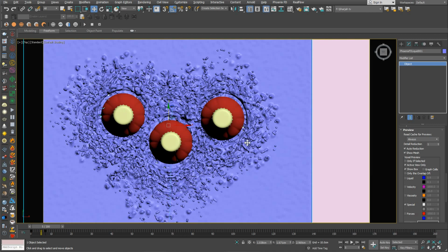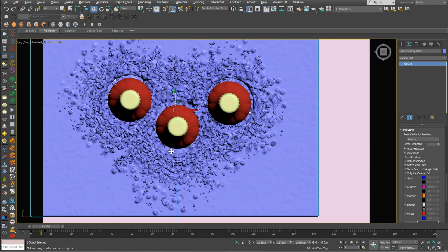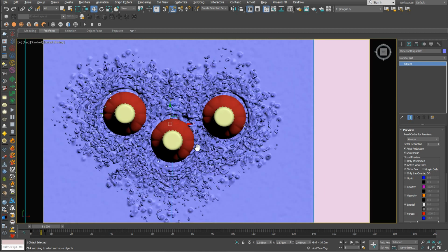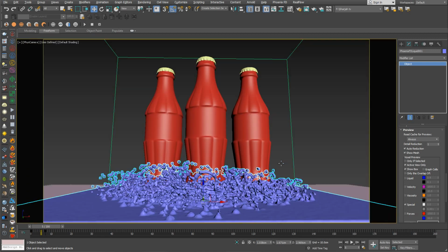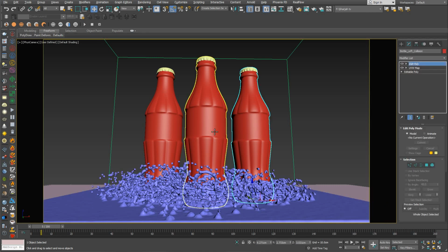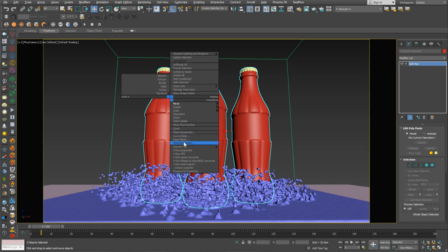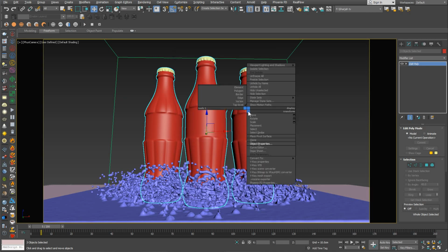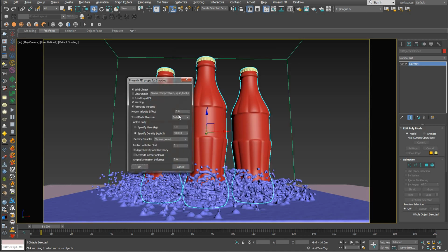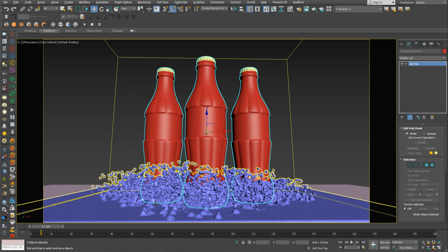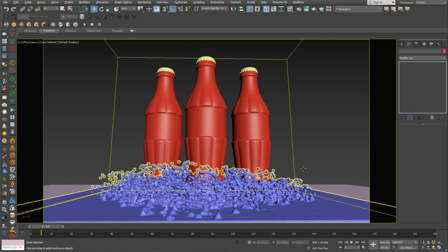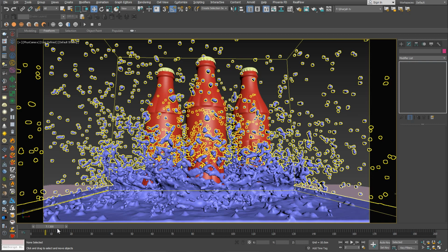Still, I can reduce this randomness here and bring the collision back to be just inside a certain place, but that's nice and acceptable. Also, I can always go here and change the motion velocity factor. You can increase it, decrease it, introduce different numbers and just see. That will affect the splash, but again, that will affect the general impact. The shape of the water is more controlled by the dynamic rollout, so that's good for now.